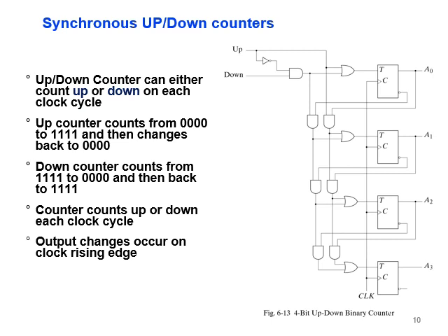Now, we can make an improvement in our counter, make it what we call an up-down counter. Up-down counter means if it is going up, we started from 0, 0, 0, 0 and we finish at 1, 1, 1, 1. So an increment. While down means we started from the end, which is 1, 1, 1, 1, and we decrement until we get 0, 0, 0, 0. This can happen by using, as you can see here, up and down through this AND gate, and here we have an inverter. So if this is 1, here will be 0, down will be closed, it will not be working. So this part, you see, will not work.